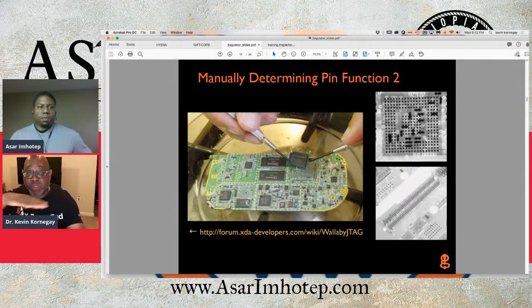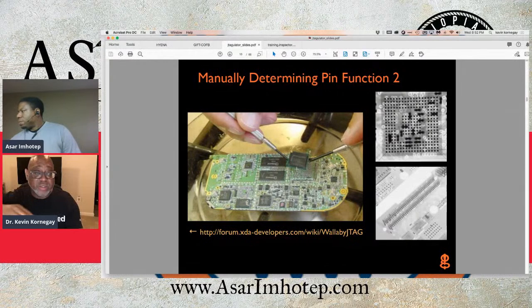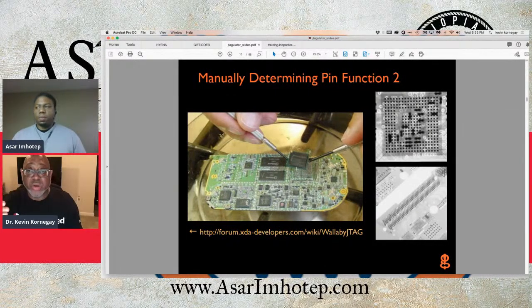Their job is to make sure that the voltage on that pin doesn't exceed a diode drop above the supply voltage. So let's say your supply voltage is 5 volts and the clamping diode is 0.7 volts. The maximum voltage that line can see is 5.7 volts. Anything above that, it'll clamp, to protect the circuit.